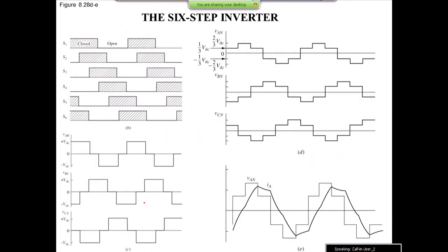So what we did last time was we looked at the very basic switching scheme. It's not PWM yet. It's not high frequency yet. It's called a 6-step inverter, or a square-shaped kind of inverter. So basically what you do is you divide your period into 6 equal intervals, like this. So this is my period. And for instance, when it comes to S1, you keep S1 on for half of the period and then off or open for the remaining half of the period.